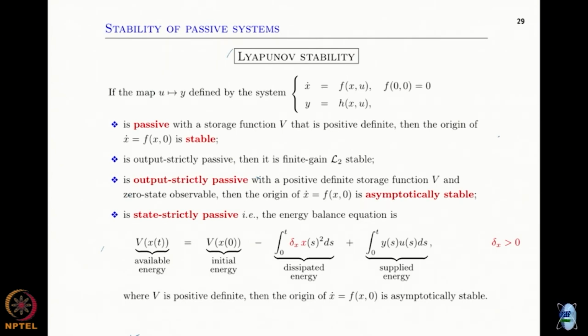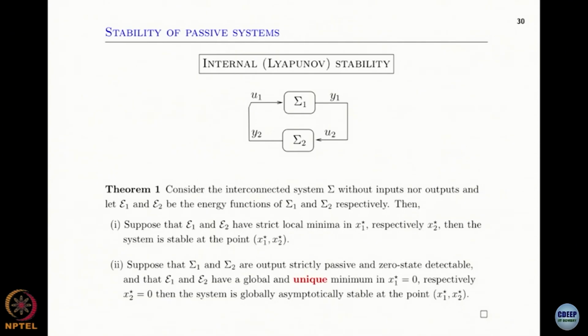So the moral of all this is that if you think in terms of passivity, you have to figure out the energy function of your system and use that as a Lyapunov function essentially, and then try to come up with some quadratic negative terms in your derivative, and the good thing is now you have an interpretation for these terms.